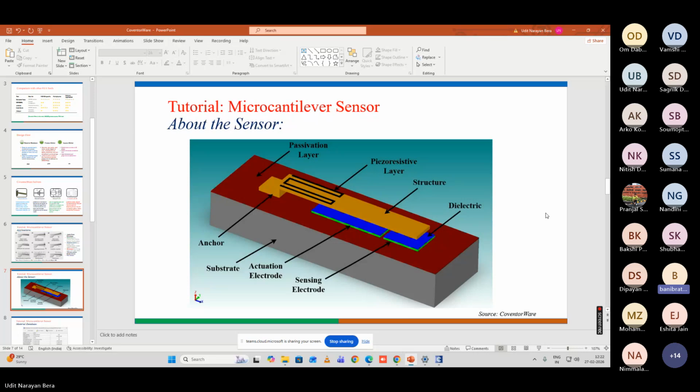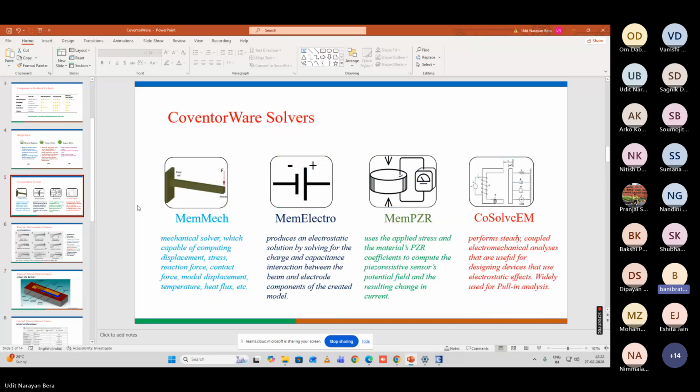So our steps will be: design, coming up with the geometry, then choosing the material, then fabricating the device, then you have to use some solver to solve it. If I apply 1 Newton of pressure, then what will be its corresponding displacement, stress, resistance change, those things. For that we need a solver using which the solutions are computed with FEM based techniques, and then finally we get the output and you can see it.